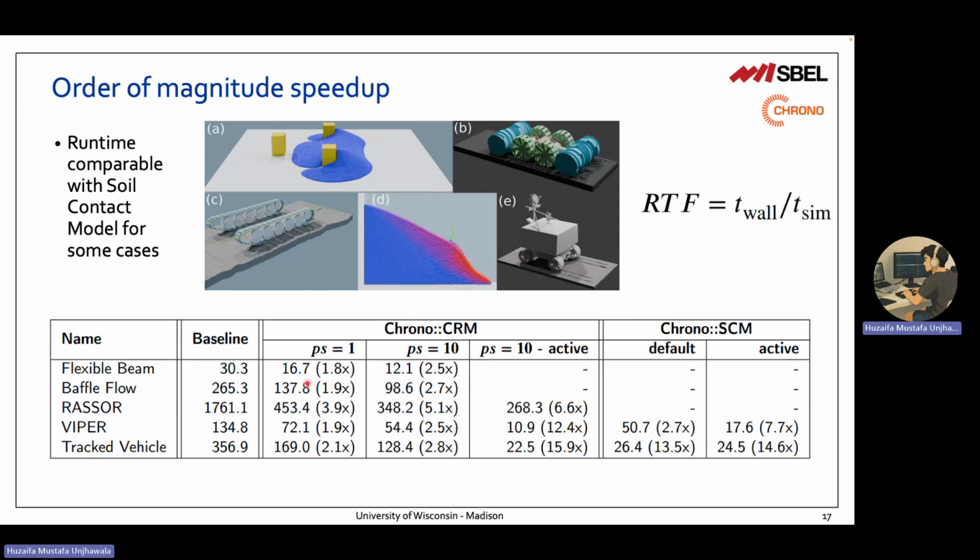And actually one of the major players in this speed up is, there's actually more to say about why the baseline was slow rather than why PS1 was fast. Before, even though we have an explicit co-simulation, like we exchange information, we used to step the MBD system, wait, and then step the FSI system. Now we just have another CPU thread that launches the FSI system and steps it. Sorry, the SPH system and steps it. So that's like almost like a guaranteed 2x, not guaranteed 2x, but like 1.5x right there. So that was actually one of the major improvements for PS1, I would say, more than the micro optimizations.